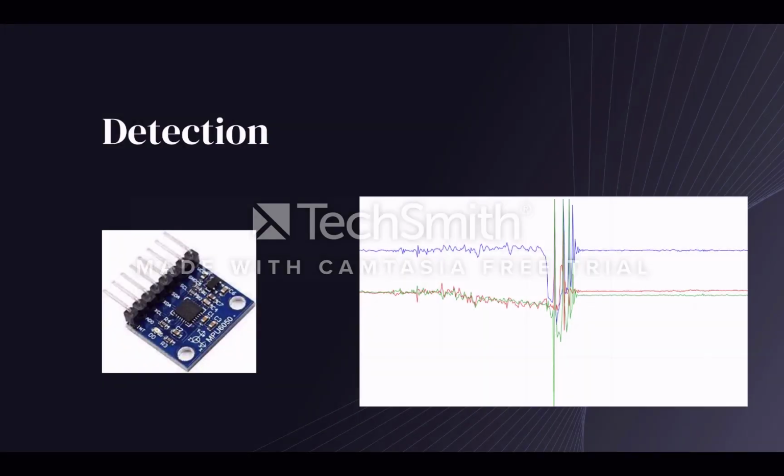Our detection system for our project utilizes an MPU 6050 to detect changes in acceleration. Using the X, Y, and Z accelerometers, we are able to detect the device is in free fall due to the lack of gravity being present. From there, we are able to tell the duration of the fall and the force that was applied in order to arrest their fall.